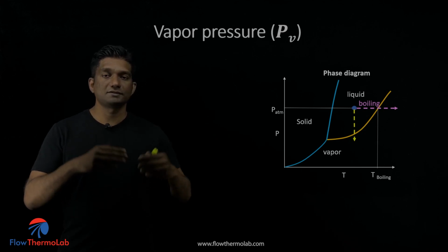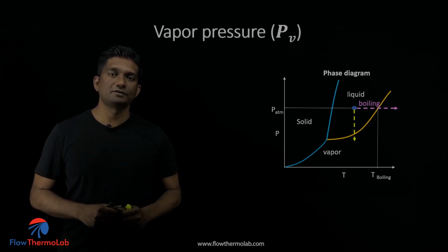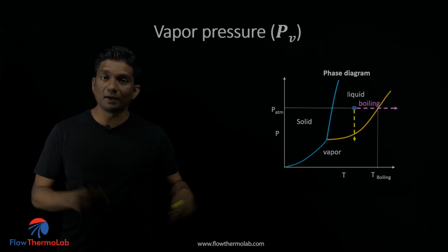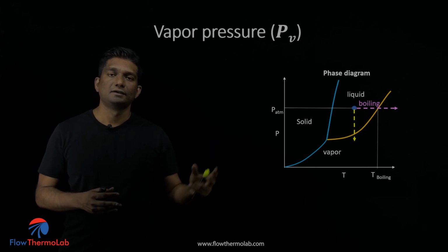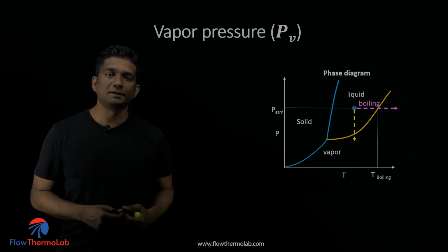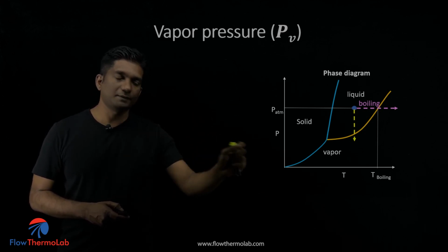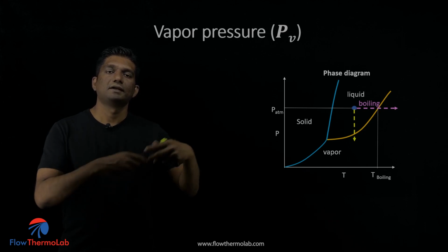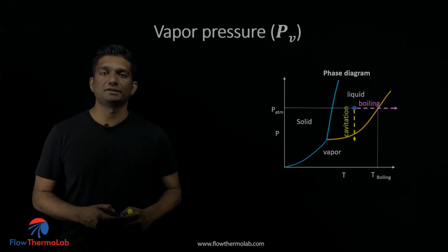So in this process, when you are increasing the kinetic energy, or the velocity of the liquid, the static pressure goes down in the same manner. You can see it in pumps, in orifices, in any other throttling devices, or valves, and many other applications. You can see the pressure getting dropped, and it will go below the vapor pressure, or touch the vapor pressure, and then it will suddenly start becoming vapor. This phenomenon is called cavitation.